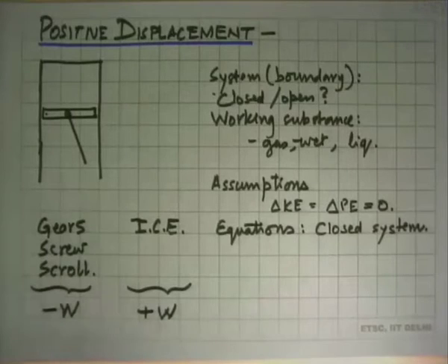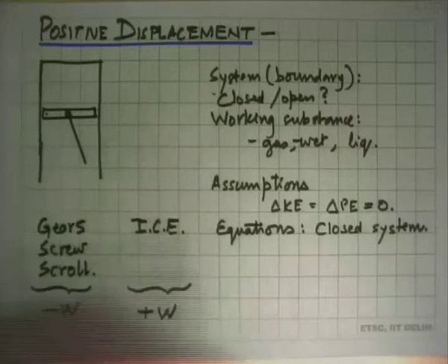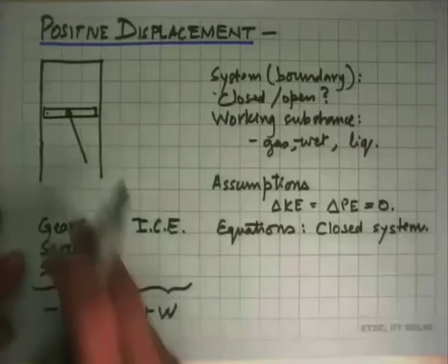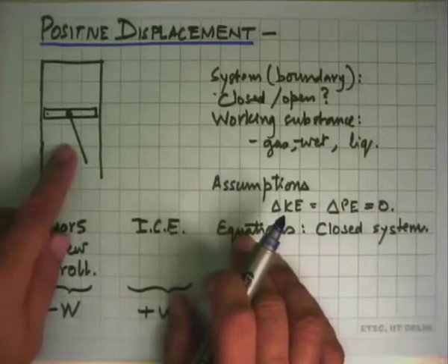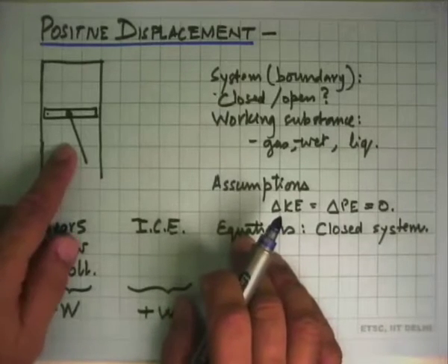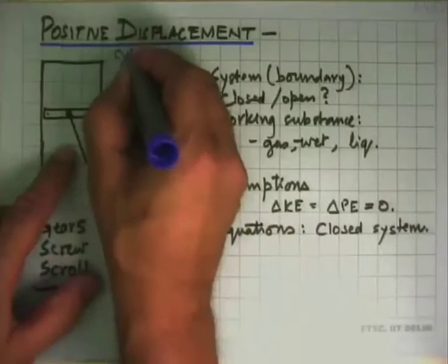And by positive displacement, we mean that once you have a substance taken inside a device, no matter what the outlet condition, when you operate it, it will push it out. There is no way that it will just stay inside. So the way we can do it in the real world is the most classical thing that you have come across, which is the cylinder piston arrangement.